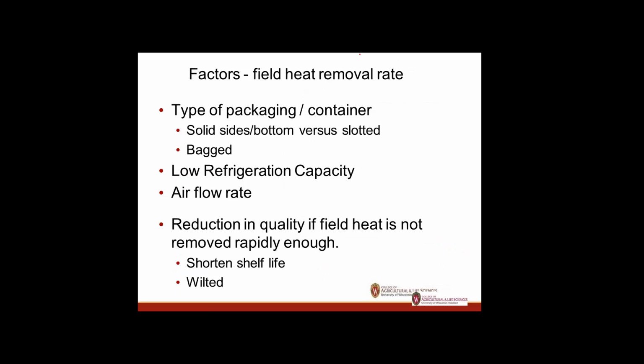So factors for removal of field heat. One can be the type of packaging or container we put it in. If we have solid sides and bottom, we're not going to get airflow through that, versus slotted sides and bottom. There was a study, I don't remember the numbers, but it was like half the time for cooling just having 10% slotted bottom versus a solid side. It's a pretty significant thing.